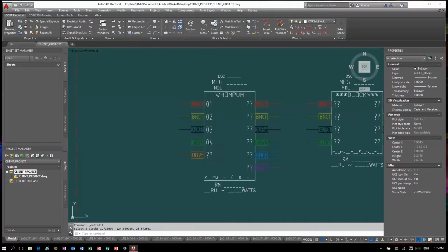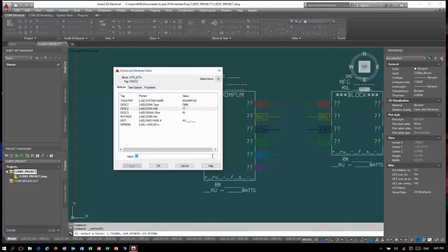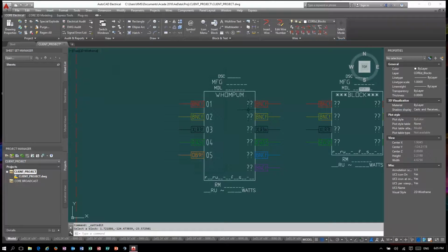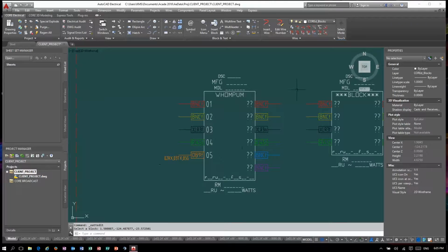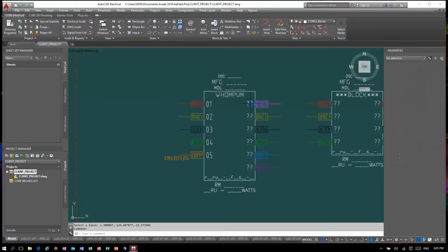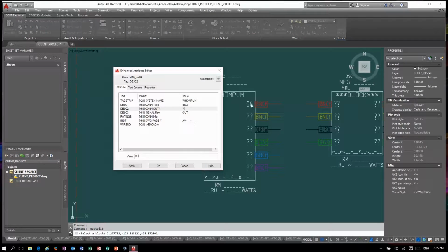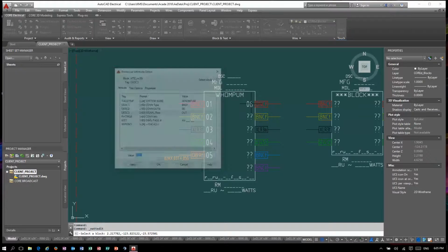This tool was purpose-built to globally update flag and equipment information, calculate power and heat loading for each room, rack, and device location, then modify specific visual reference points for viewing and archival purposes. The ultimate and primary objective of this application was to eliminate the tedious and time-consuming process required to create a 100% accurate wire run list from a drawing set.